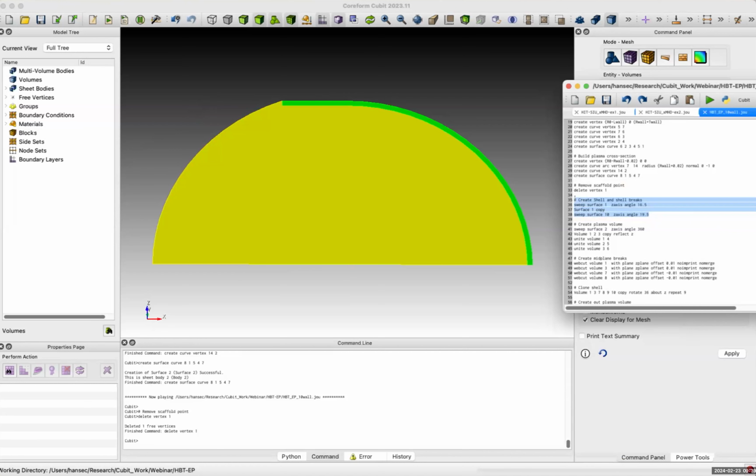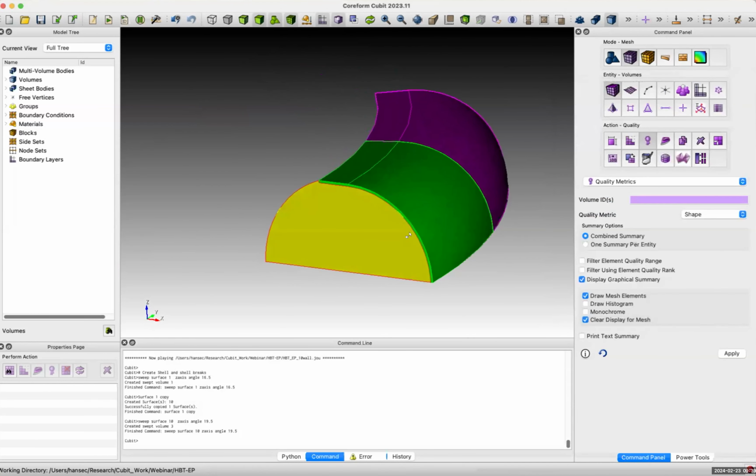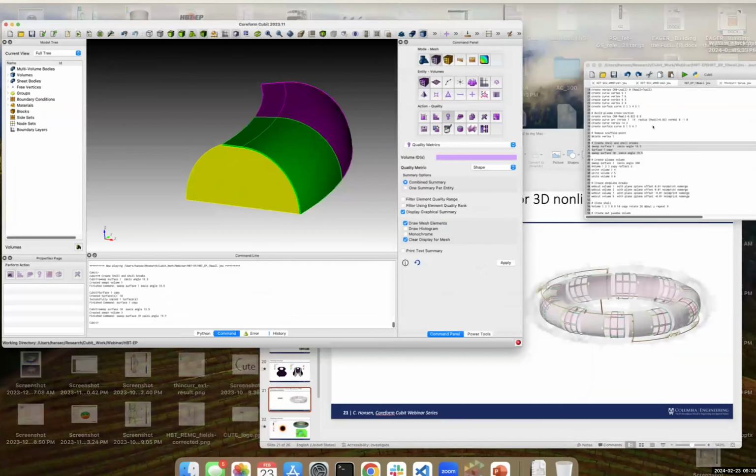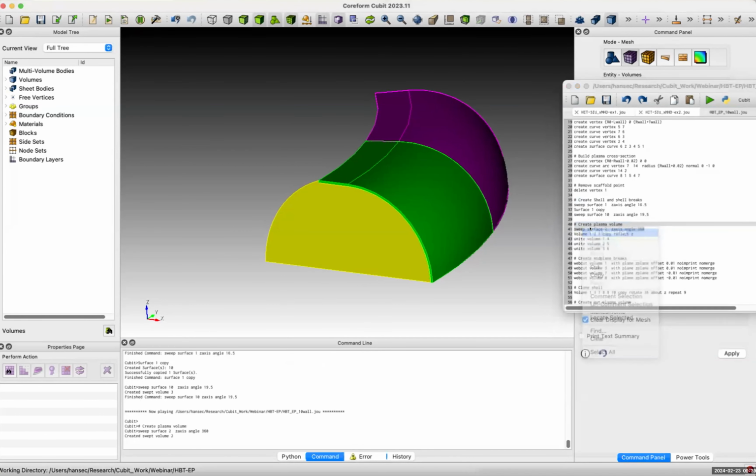So first, I'm going to sweep the shell segment around here. You notice what I've done here is I've done two sweeps. The first sweep corresponds to where the actual conducting shell is. And then the next sweep corresponds to the break between conducting shells. So each of these are going to have different physics models happening within the code once we export. Okay, so I've started this with the shell. Now I'm going to sweep around the plasma model. So I'll go ahead and do that.